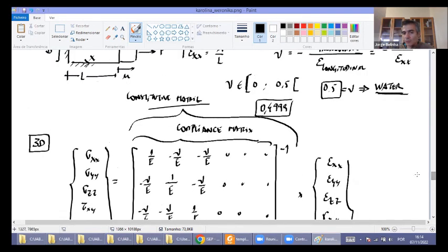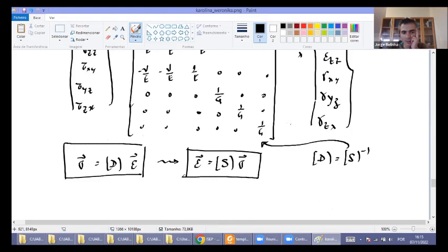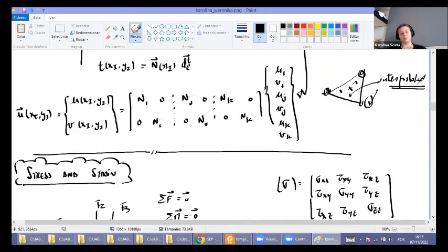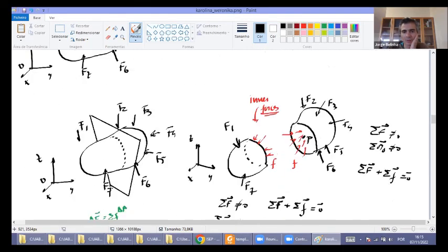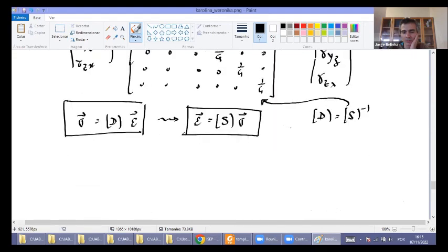And you don't have to define it. You don't have to go to the lab, because if the material is isotropic, okay, and well behaved, you can define G with the Young's modulus and the Poisson coefficient like this. You don't have to go to the lab to see what it is made of. Well, I think that with this you have more than enough to start reading the book, okay?